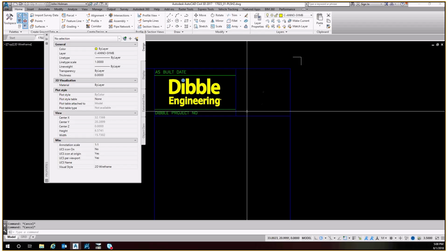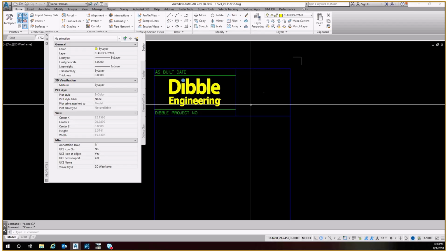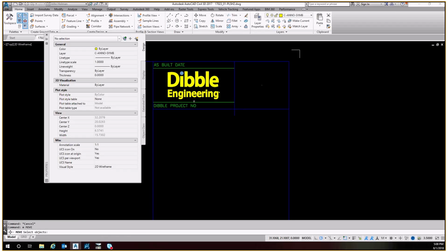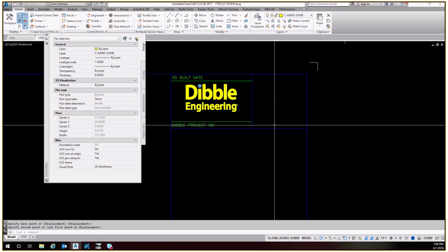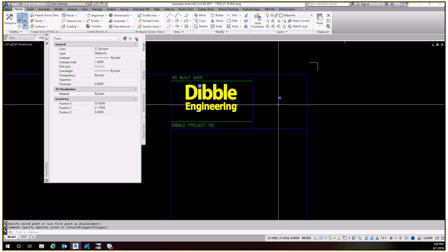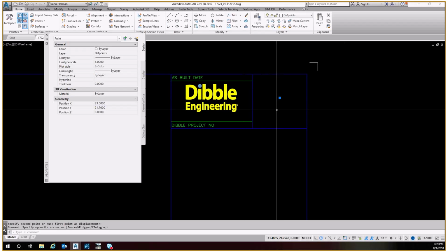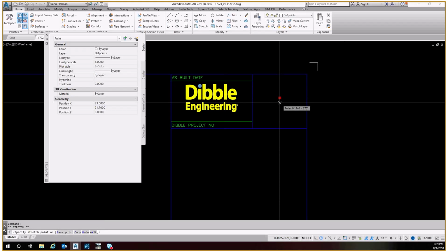So there are a lot of ways we could do that. What I'm going to do is lengthen this line here to a total length of 2. And then I'm going to move these elements here from that intersection down to the endpoint there. So now we've got a 2 by 2 space for this seal. This point is going to be off because that used to be in the center of the 1.75 inch tall box, but now it is no longer in the center. If we trust that it was placed accurately horizontally, which it was at 33.6 inches, then we can just move this down by 0.125.